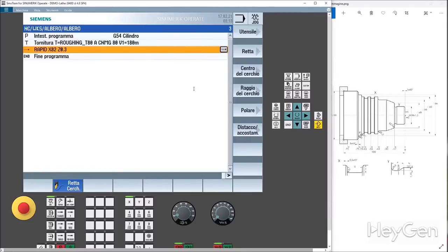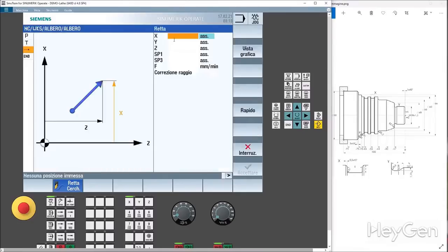So we set it to rapid, accept that, and now the machine moves close to the workpiece, so straight to X. I'm going to face it, so -1 point 6. Why 1.6? Because the insert radius is 0.8, as I already explained in the previous videos related to tool radius corrections. If I chamfer at X0, there will be a bevel left from the tool's radius that won't be removed all the way to the center of the piece.